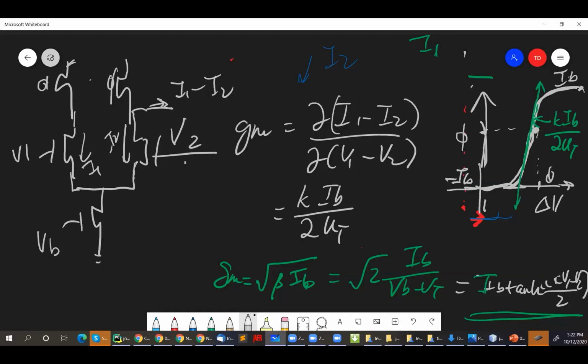Again, they have to be connected, same gate voltage, same VS. Then, of course, you have to have the gate driven by something. We notice in exams, sometimes people don't draw what the gate's connected to, except to each other. So for the thing that sets the gate voltage, you have to tie the drain to the gate. It's a PFET, so remember the drain is lower than the source.